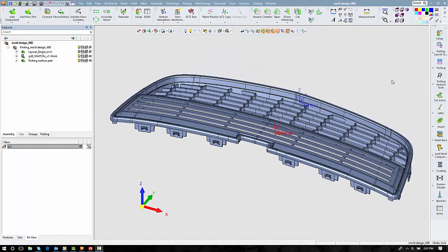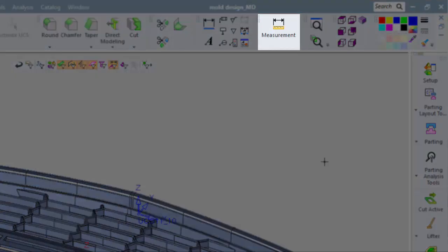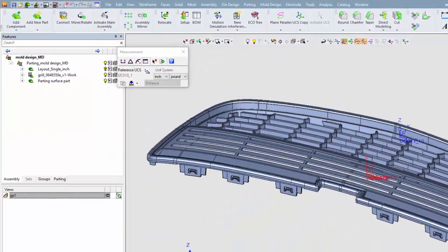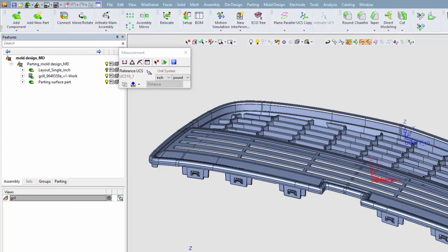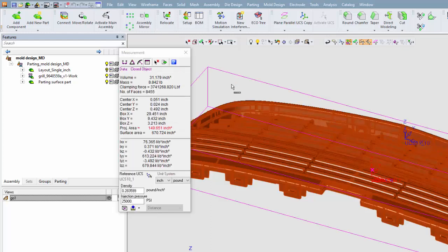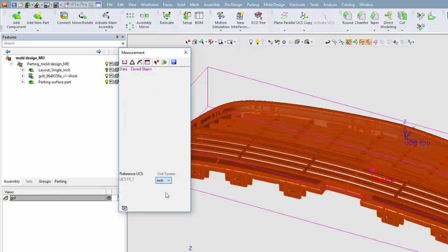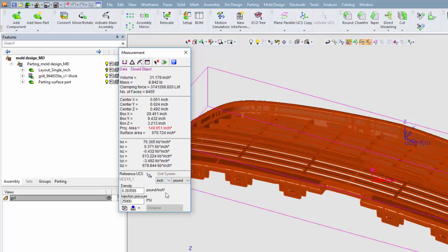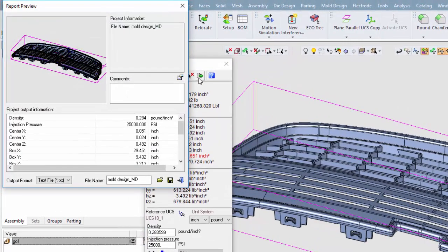This takes us to our next analysis tool, which we'll use to get measurements. In addition to having nice tools for snapping quick linear measurements, such as from point to point or point to line, it will also measure angles, angles between faces, between edges, find the radius of curves, individual curves, or filleted surfaces, and it will give overall dimensions, such as an overall XYZ box, the ability to find the mass and the overall volume of the part.